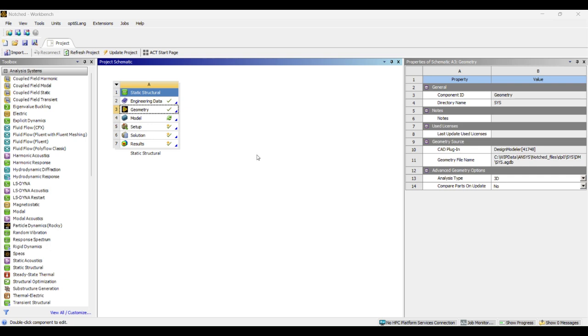All right, welcome everybody. In this video, I'm going to teach you how to submodel in ANSYS FEA. Submodeling is an important part of finite element analysis, and you'll see why. Essentially, what submodeling is, you create a smaller model that's representative of a feature in your geometry that you're concerned about, say a stress concentration.